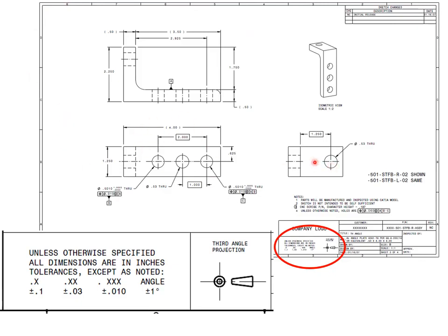So we have front view, side view, top view. One of the mistakes I see right off the bat is, notice how this leader is floating upward. I should have done the same thing with these other leaders here. Should have had them floating upward.